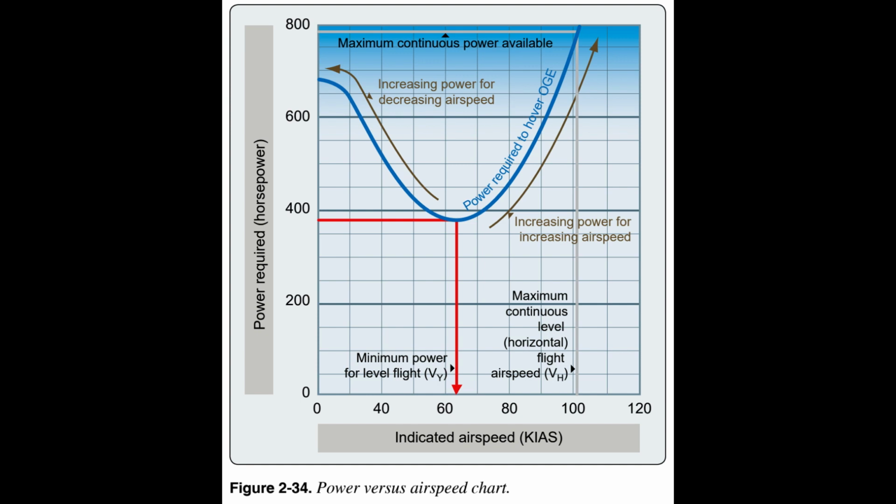Airflow across the rotor disc in forward flight varies from airflow at a hover. In forward flight, air flows opposite the aircraft's flight path. The velocity of this airflow equals the helicopter's forward speed. Because the rotor blades turn in a circular pattern, the velocity of airflow across a blade depends on the position of the blade in the plane of rotation at a given instant, its rotational velocity, and the airspeed of the helicopter. Therefore, the airflow meeting each blade varies continuously as the blade rotates.